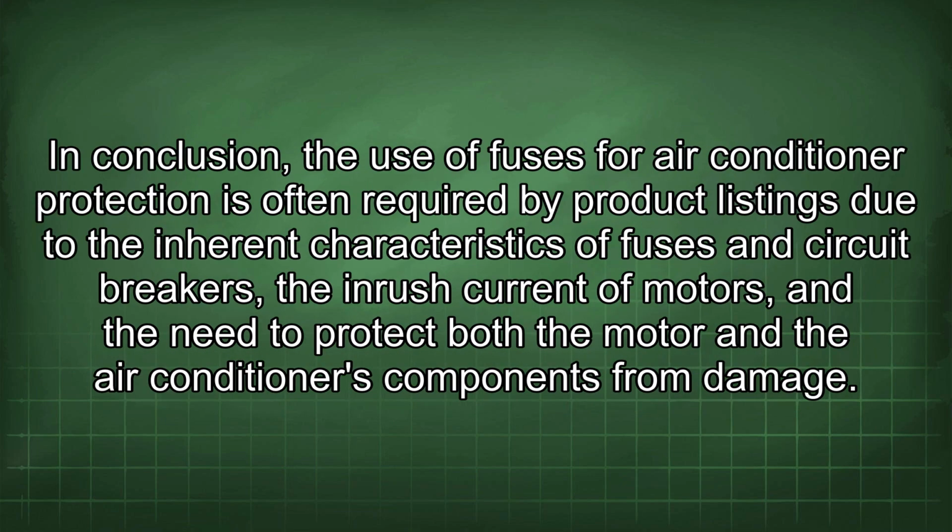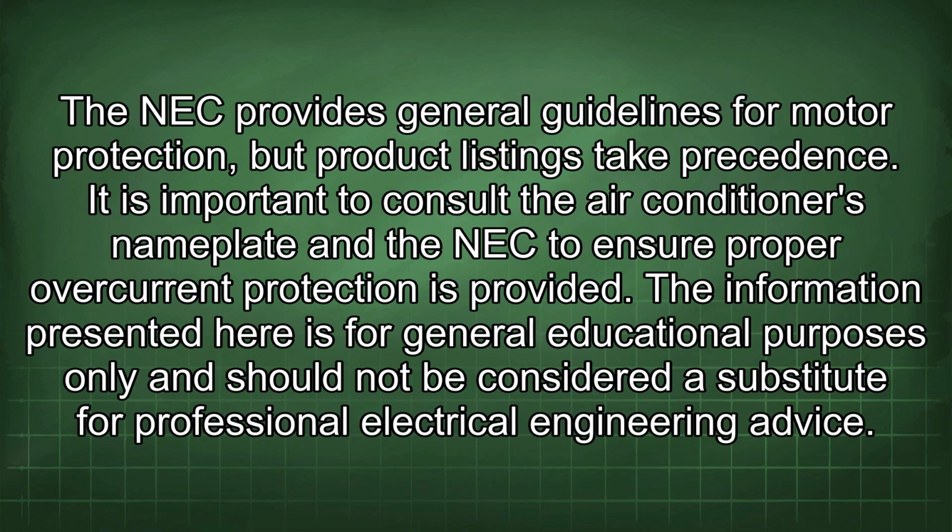In conclusion, the use of fuses for air conditioner protection is often required by product listings due to the inherent characteristics of fuses and circuit breakers, the inrush current of motors, and the need to protect both the motor and the air conditioner's components from damage. The NEC provides general guidelines for motor protection, but product listings take precedence. It is important to consult the air conditioner's nameplate and the NEC to ensure proper overcurrent protection is provided.